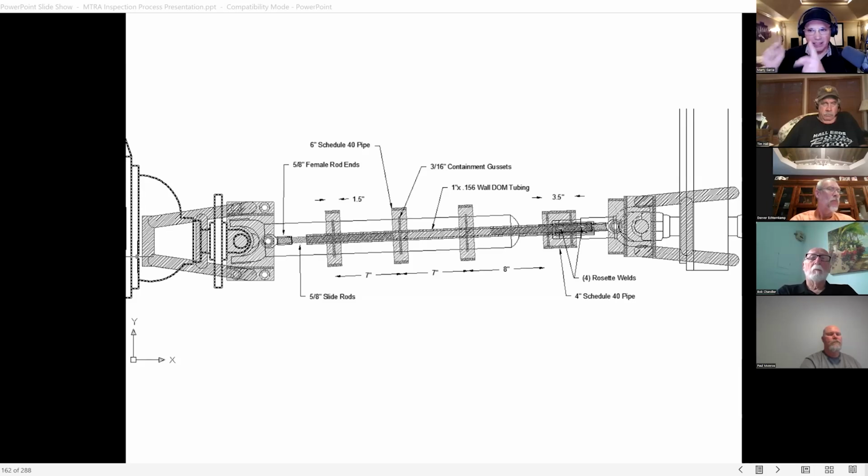And the stub itself is a smaller piece that can escape if you don't have that smaller diameter tube in the right spot. So it's very critical. The placement and the distancing between those loops is critical. A lot of guys are buying them. Most of the trucks nowadays, they're buying them from Patrick or something, and they're pretty standardized. But if you're seeing something that doesn't look like a conventional loop setup, you definitely want to check the specifications, make sure everything is up to our standard.